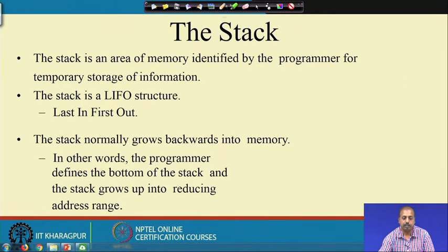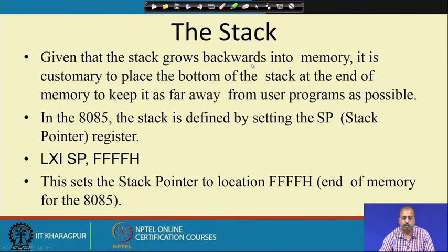Now, we will see how this happens in the 8085 processor. Given that the stack grows backwards into memory, it is customary to place the bottom of the stack at the end of memory to keep it far away from the user programs.